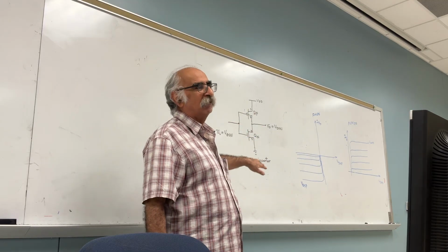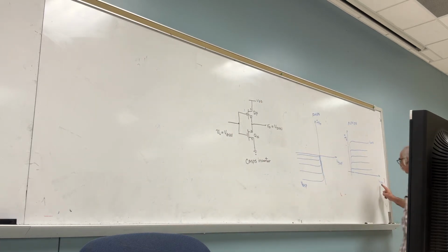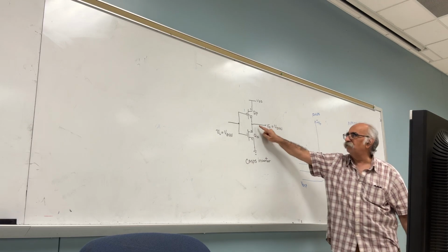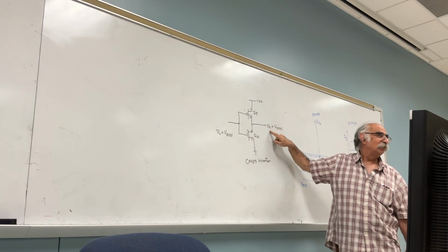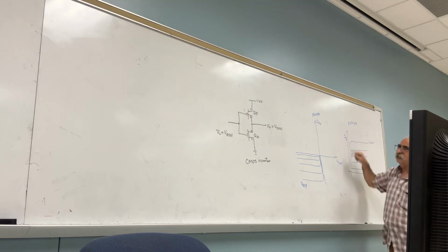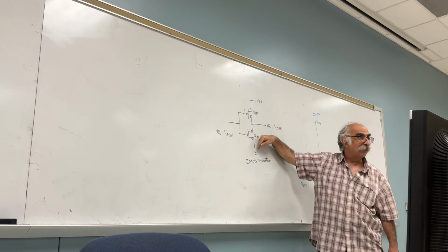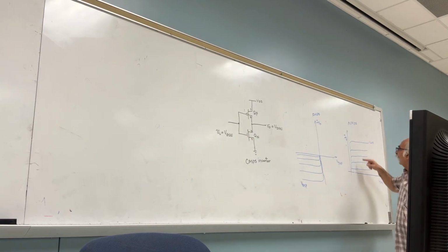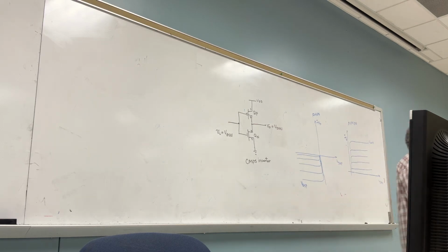The first thing to do is to look at each one of them separately. The NMOS. Let's see if it rings a bell. What do we have here? VDSN, which is the voltage from the drain to the source. That's the same as Vout. Did you get it or not? This one is ID, which direction? Down. Clear? Okay, good. And VGSN, which is the same as the input. Clear so far?